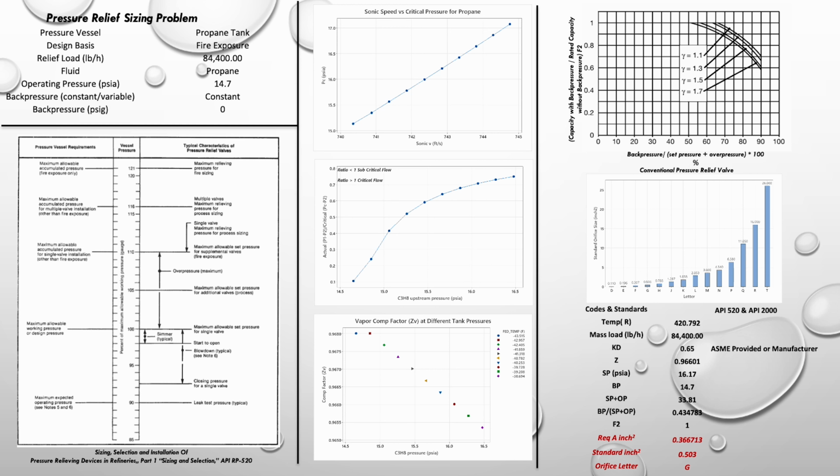There is actually, beyond the simplistic view of relating the critical pressure and the upstream pressure with the specific heat ratio, another relationship between the sonic speed and the critical pressure. And the sonic speed is way stronger, because it doesn't matter if it's ideal or real gas, it is a generalized formula. It's going to tell you, here is your sonic speed and here is your critical pressure.